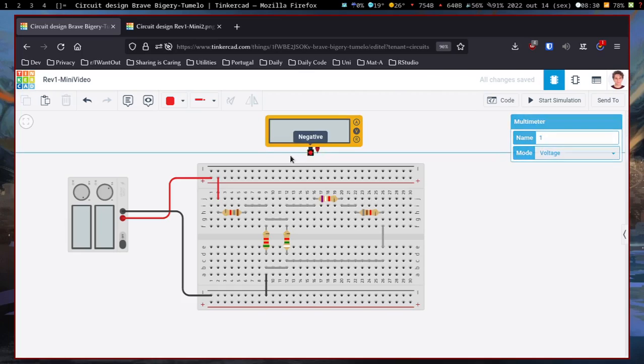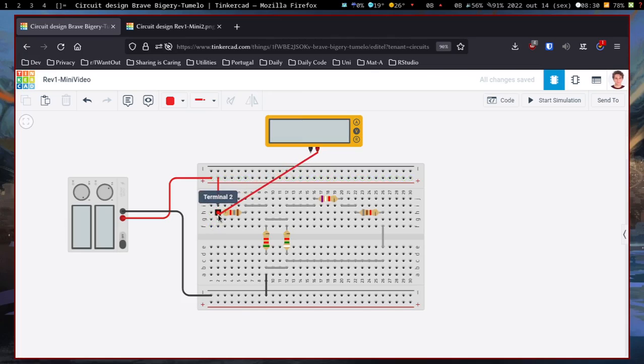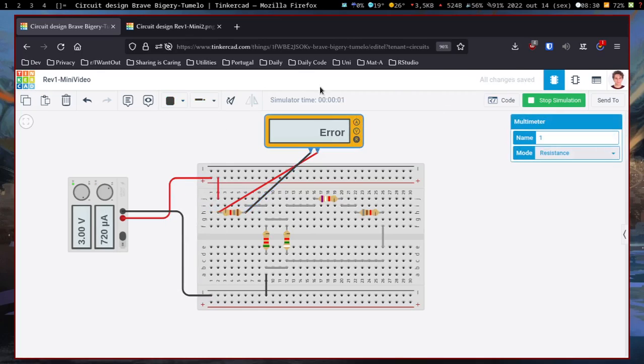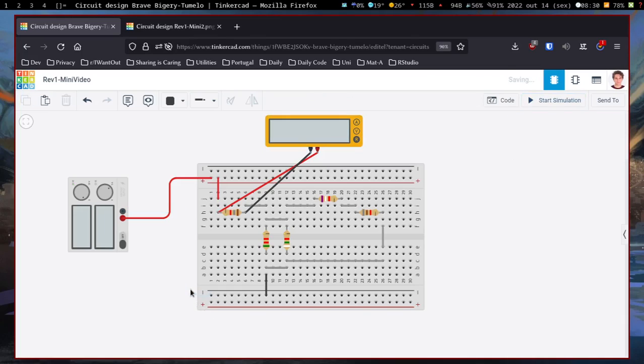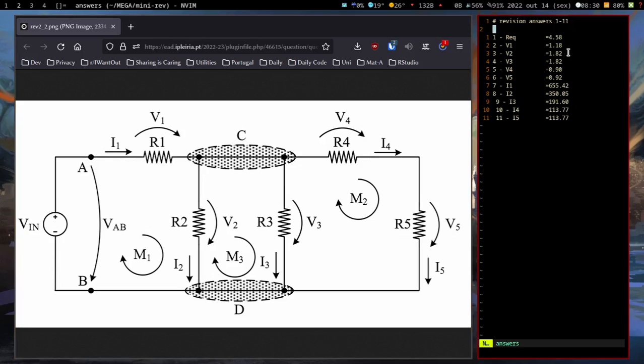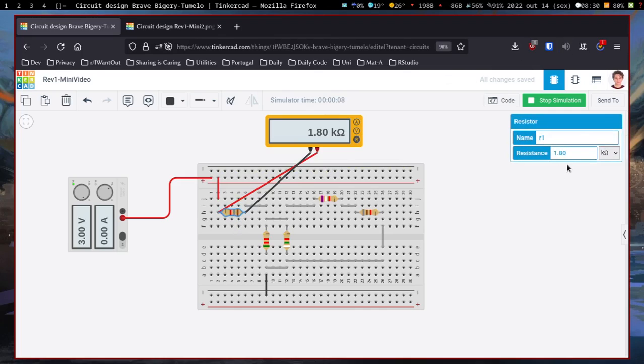To get the resistance, we need to put things in the multimeter in parallel. And it didn't work. This happens because we are still running our circuit. For this to work, we need to cut the power right here, allow one thing to flow in, and we get a result. It happens to be just right, because that's the resistance.